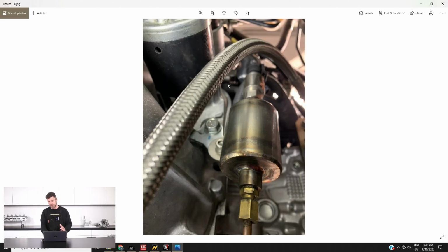Then this is actually the back of our Toyota 86. So we're running exhaust manifold back pressure on that as well. This is a slightly different system from T1 Race. Again, I'll show you that in a minute. So this is just a fabricated stainless canister. The idea behind it is essentially it runs a very, very small restriction on the inlet side, and then the actual sensor, which is a little bit fuzzy up the top there, that's just another Honeywell 150 psi pressure sensor, is mounted on the other side, and it just again smooths out that pressure signal.